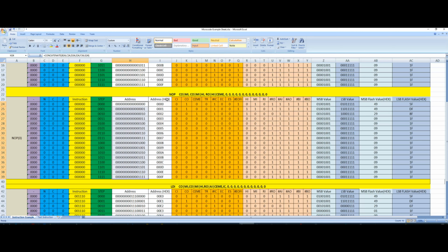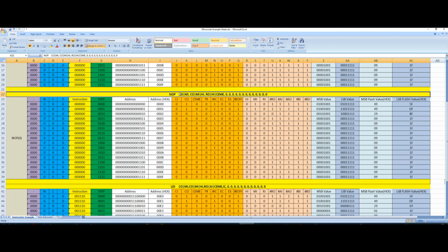If you don't want to do anything in the computer, you're just going to call upon this instruction, right? However, despite the fact it doesn't do anything, it still needs to have the fetch instructions. As I mentioned before, the fetch micro instructions should be part of any instruction in the computer. As you can see here inside the no op, we really don't have anything other than the fetch cycle, which consists of 3 steps.